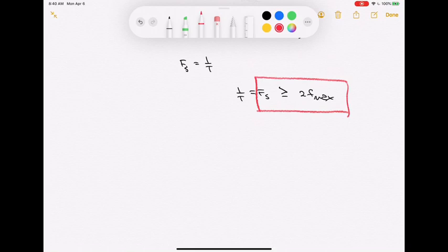And that sort of makes sense. If you sit there and think about some sinusoid going along, if I really want to capture something about its oscillations, I better be able to get those peaks. I better be able to get something that tells me that it's oscillating along. 2 samples per period. So the limit, if I want to make sure that I'm not aliasing, I must be sampling at greater than or equal to 2 f max. This is called the Nyquist criteria for sampling, or the Nyquist criterion, or the Nyquist condition.